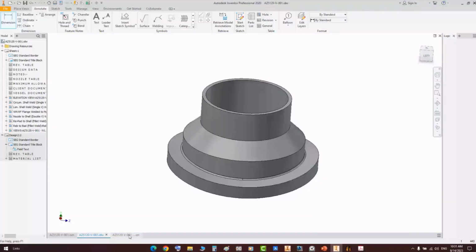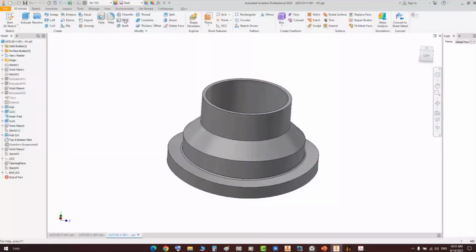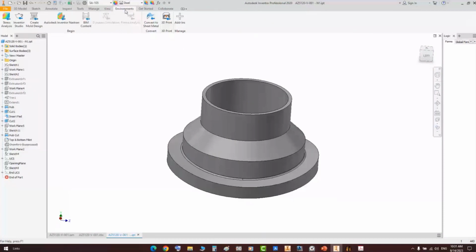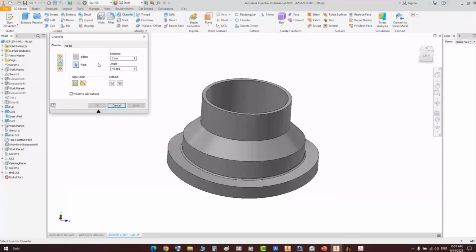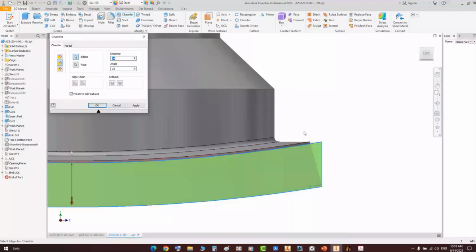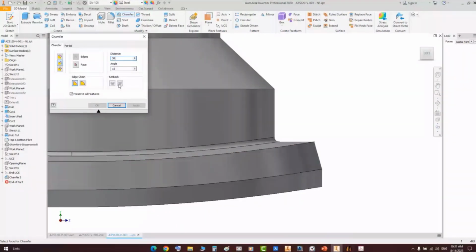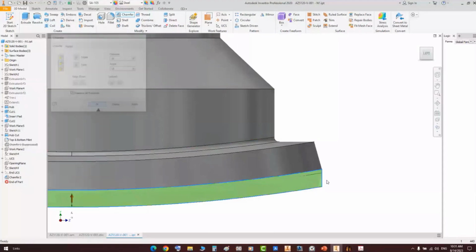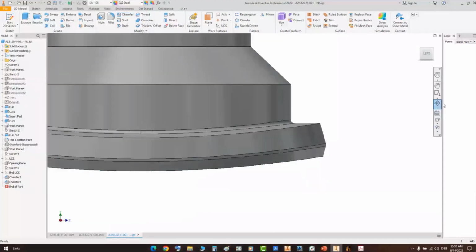For example, in this one, as discussed, if you would like to make a chamfer, you can make a chamfer for this nozzle. So let's make it with 15 degrees and the distance, let's say 95, and select this edge. But as you can see, you can make a chamfer on one side. And if you would like to make it on two sides, let's make it 60 millimeters, and make another one with 30 millimeters. So let's select this edge. So you can make a double V chamfer on this hub.